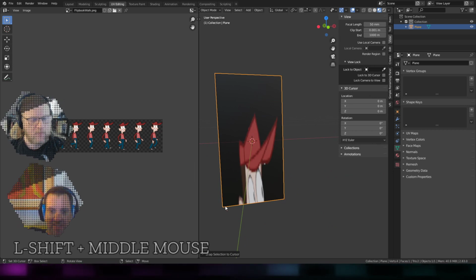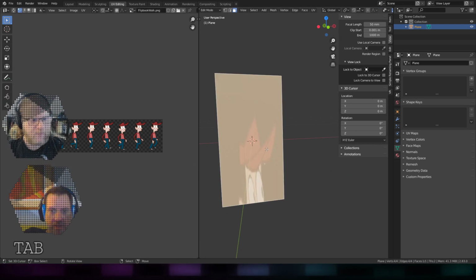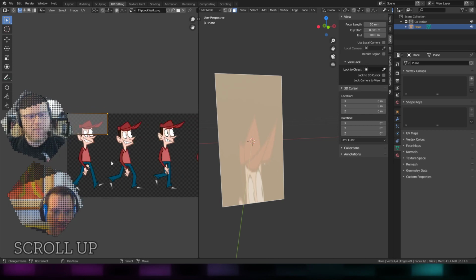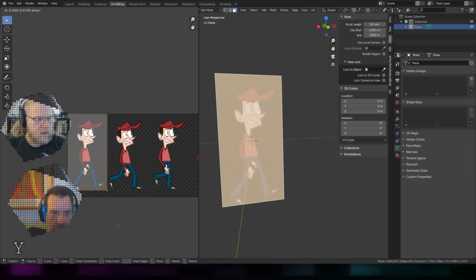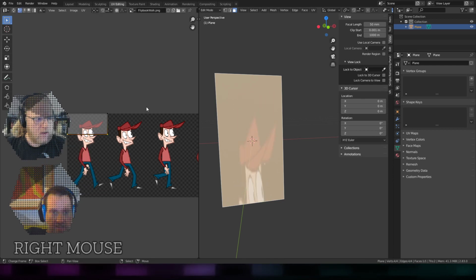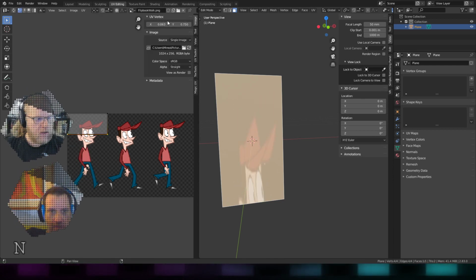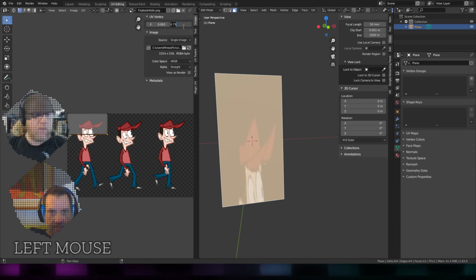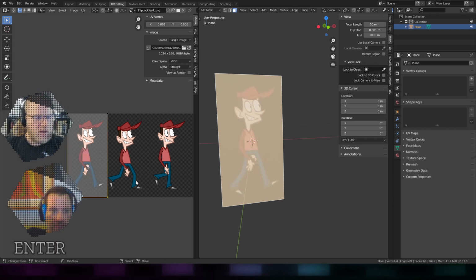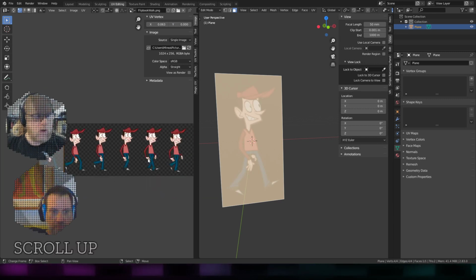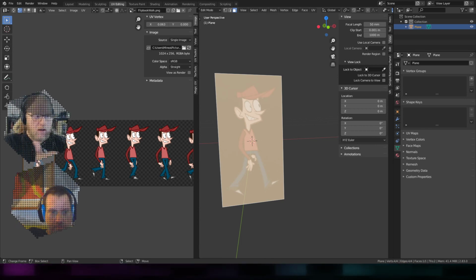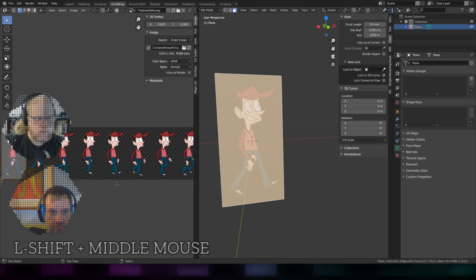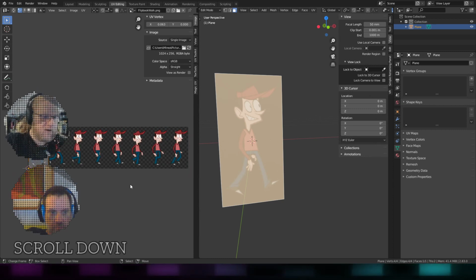So now this is the right size, but its UVs are wrong. So all I have to do now is just pull these down to the bottom, and then it's the right size. And if you're really being particular, you could set, I mean, you know exactly what the value should be. The bottom ones should be at one for the vertical dimension, and then the horizontal dimension should just be one over, or divide by, the number of sprites.